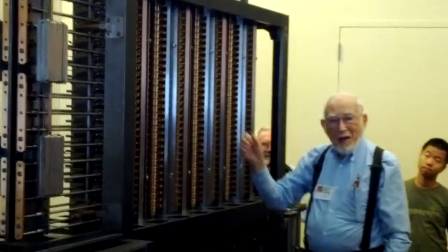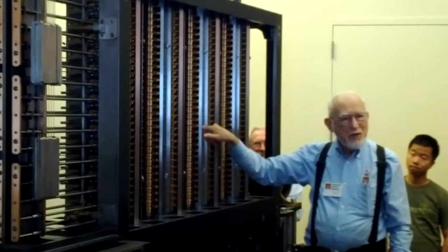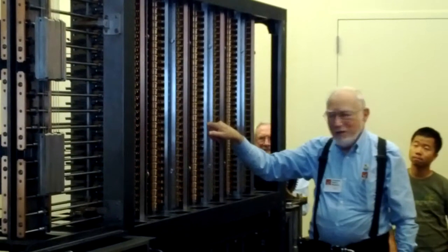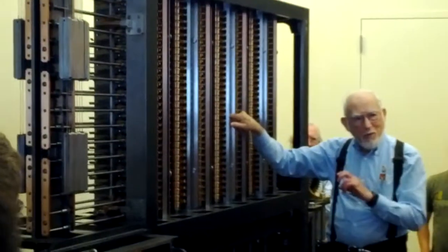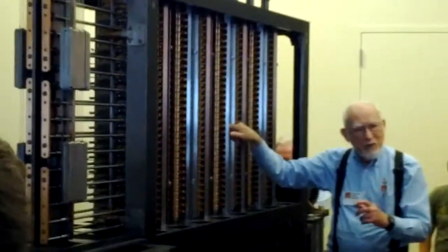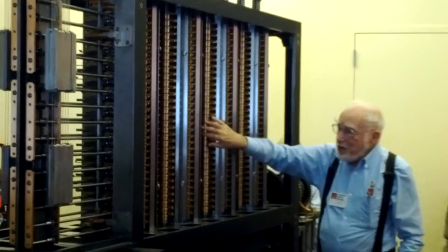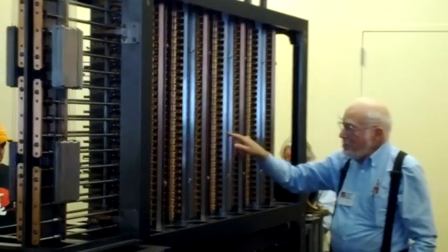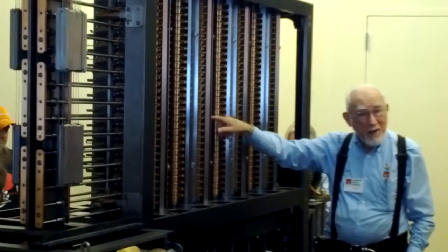So it's looking at the number. And that rod rotates. And what it does is it sets each individual wheel to 0. There's an index mark. So if a wheel was showing 9, it would be moving all the way around. If it's showing 0, it wouldn't move at all. And because it's connected to this gear, which is connected to these teeth, the number in each one of these wheels is added to the number in this wheel.